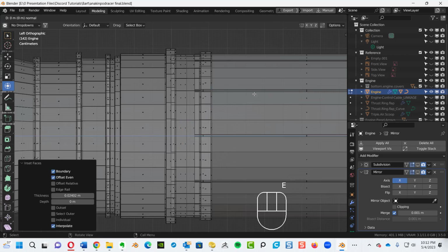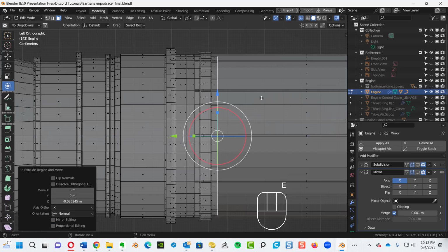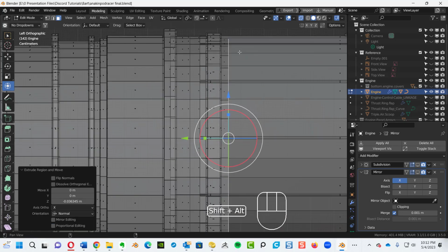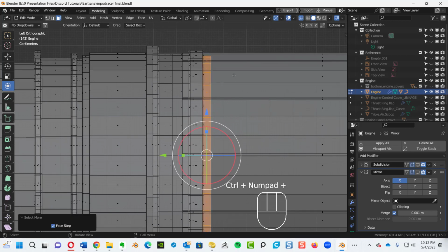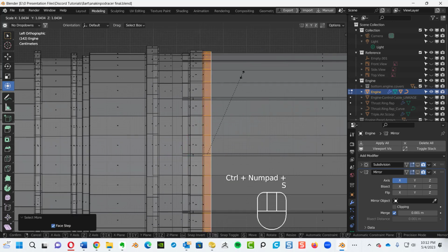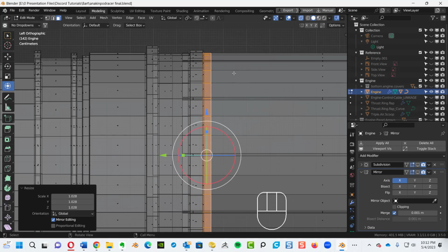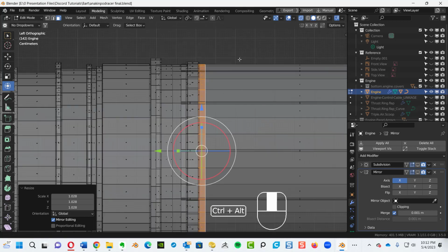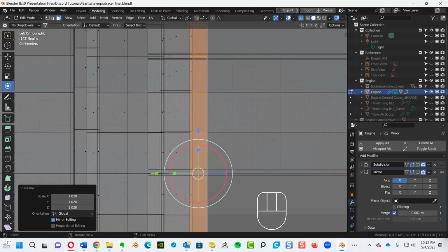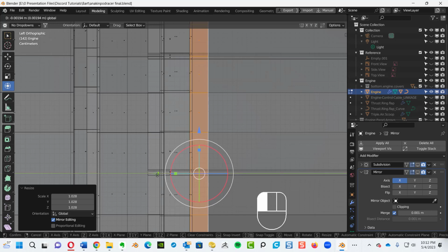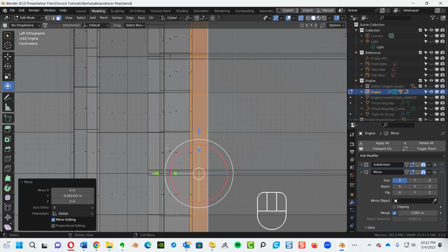All right, let's hit E for extrude. Oop, that was just a little bit too small. Control plus. S, scale it out. Okay. I'm going to push this forward, and why is because I want to make sure this interior is going to match. It's going to be flush back in there, right along that little edge there.